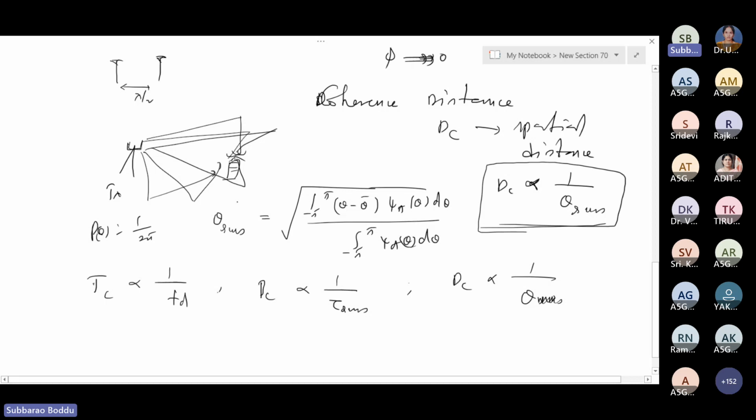So at the user equipment, we can place the antennas very close to each other, because the angular spreads at the user equipment and the base station are different. Whereas at the base station, to get uncorrelated signals, we need to place the two antennas far apart. It depends on the channel fluctuations; that is, we need to know at what distance the signals are uncorrelated.